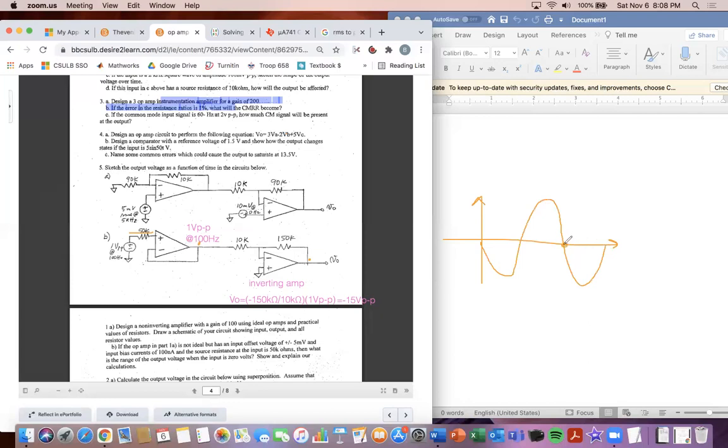And so we know the period here, it's going to be 1 over the frequency. So 1 divided by 100 gives me 0.01 seconds. So 0.01, and this is time in seconds. And then for my y-axis, this is going to be up to 7.5, because peak to peak, divide that by 2, and negative 7.5. Okay, that's how we got those values there. And that is how you do 5A and 5B.